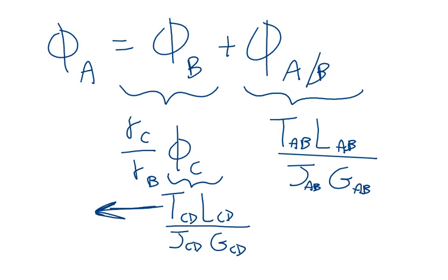What is the torque in CD? Well, gear C is connected to gear B, and gear B is part of shaft AB, right? So basically, that's the amount of torque that gets transmitted from the first shaft to the second shaft. I'm sorry, let me erase that. That's going to be RC over RB times the torque in AB. That's torque CD. Okay? Torque CD is equal to that.